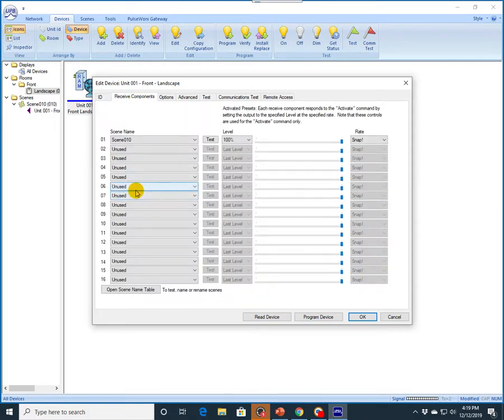By default, all UPB devices come with some links in here. It doesn't matter where, and I use the term links interchangeably with scenes. Link was the original name used within UPB for many years. A few years ago, Upstart changed from link to scene. And so if you see the term link or the term scene, those are interchangeable.